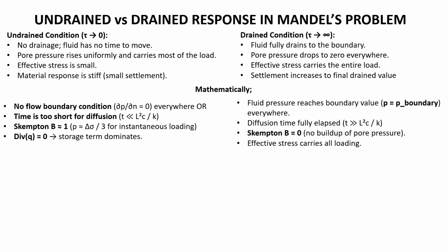Mathematically, this occurs when diffusion time is large enough that pressure equilibrates across the medium. In this case, Skempton's coefficient B is equal to 0, meaning there is no pressure buildup. The rock frame carries the load entirely, and we can say this is no longer a storage-dominated region.